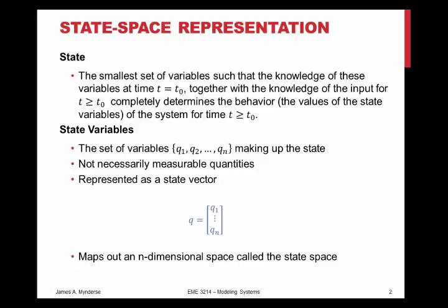Also, if you needed to transform the system, say you were doing some modern control and you needed something a little more mathematically tractable, a little easier for the computer to crunch, you might apply a state transformation where the physical significance of both of the states would be lost, but they would still be a state whose value tracked the system and would allow you to determine everything about it. But in that case, it's not a physical measurable quantity anymore, it's just an arbitrary number.